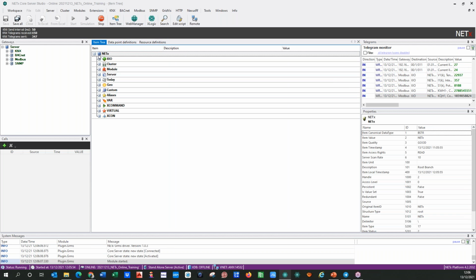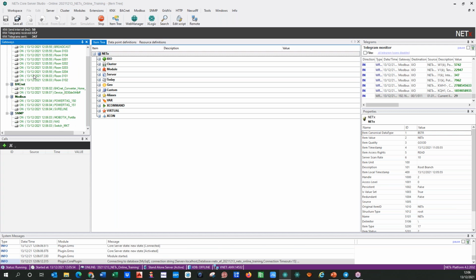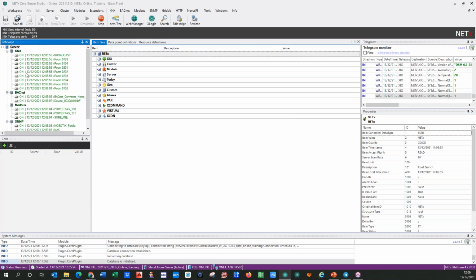Every minute we see different protocols that we can also integrate. So take a look here. We are in connection with 4 different protocols natively, without any gateways between KNX and BACnet, without any gateways between KNX and Modbus, because the devices are Modbus TCP. We don't need any gateway, or even if they are Modbus RTU, we just need a Modbus TCP gateway that is cheap, and we get it in the BMS.